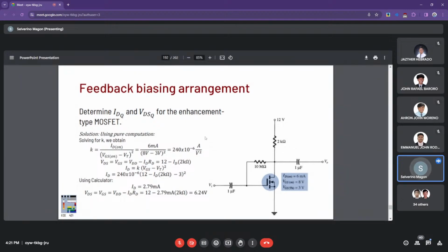It has a weird looking unit, but this is just a multiplier to balance things out. The unit is amperes per volt squared, right? After that, this can be useful for later calculations of drain currents. But for now, we will go through the drain-to-source or the output loop.